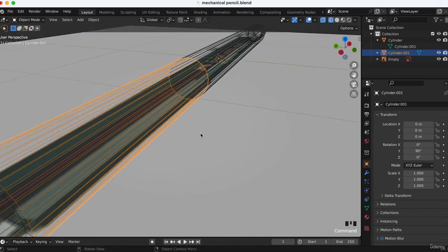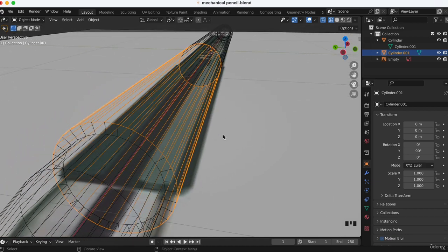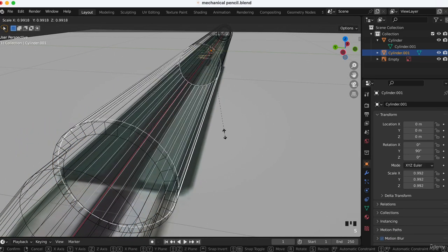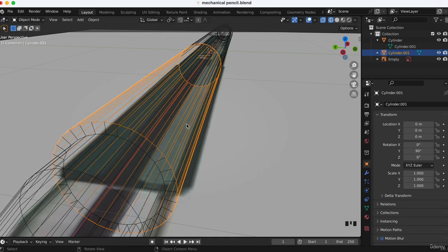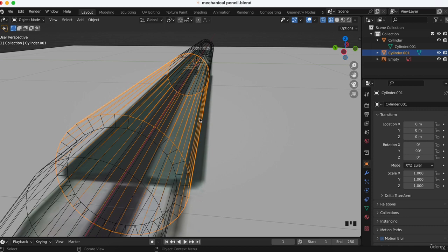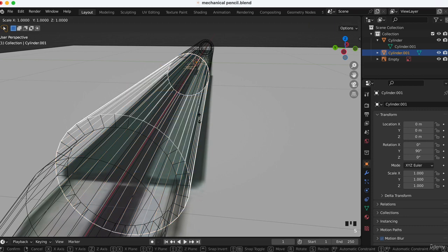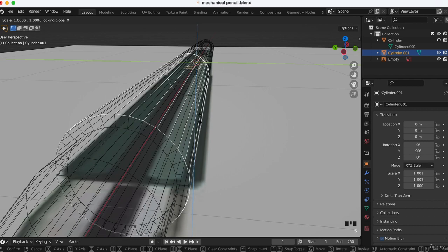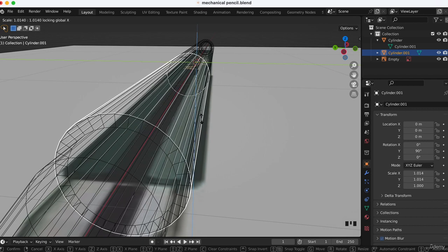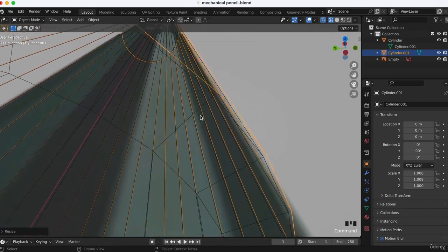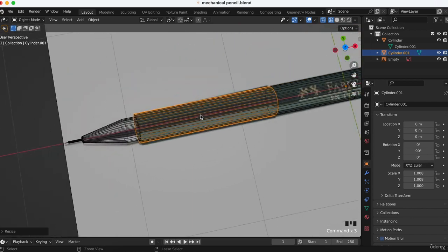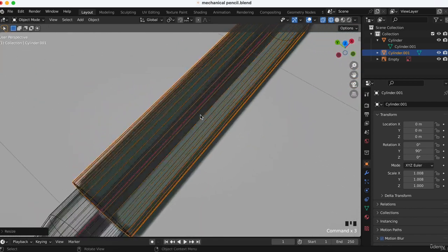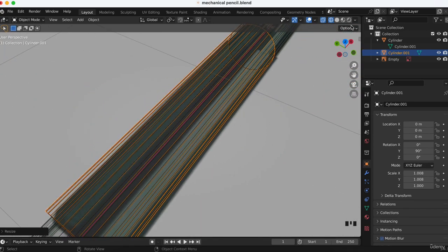This part we are going to make a little bigger, S, but not on X like this. We just want it on Z and on Y. So S, Shift X, like this, a tiny bit like this, and then we can create this effect that is not smooth.